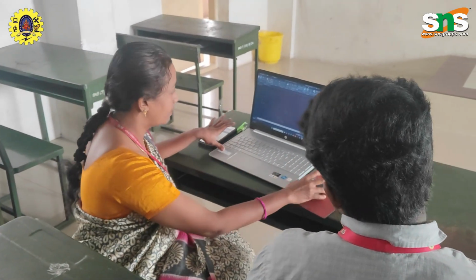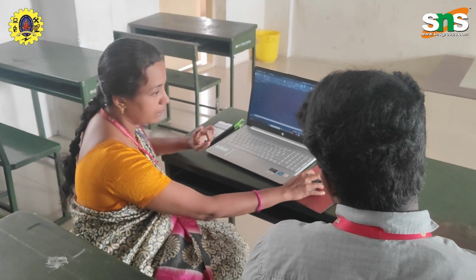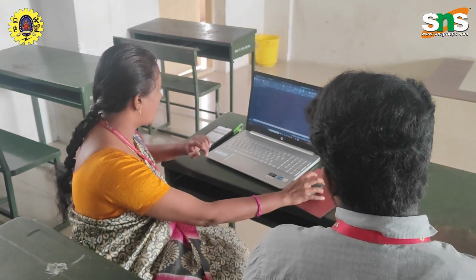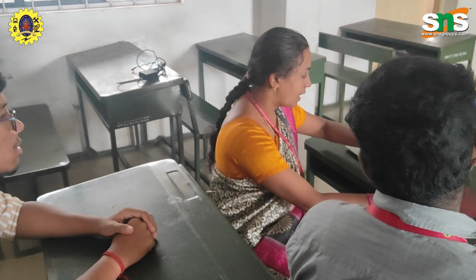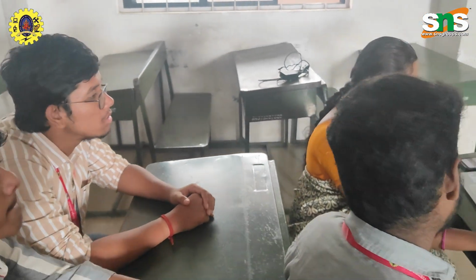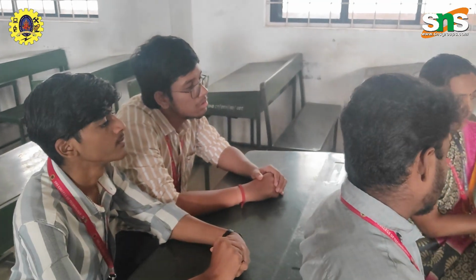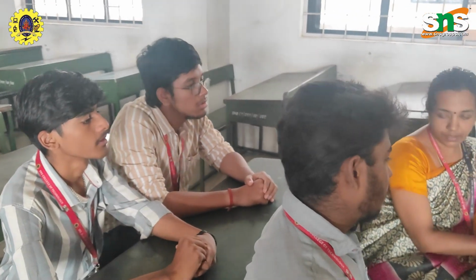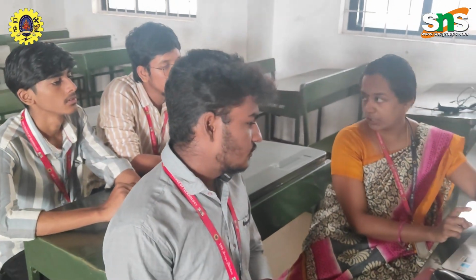That is the best option. Now I have drawn a line of 40 centimeters. Again I have to draw a line of height, and the height is 10. So I move to the left. If I change direction, there is no fluctuation at 150 degrees because ortho mode has been turned on.